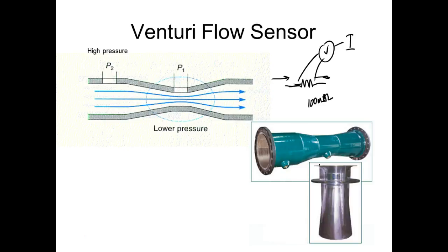Now your milliamp scale is probably going to have like a 100 ohm resistor in there, but you've got to remember that's milliamps, right? Even if 1 milliamp flows through a 100 ohm resistor, it's going to drop 100 millivolts, which is not going to be enough of a problem. And you can measure this. You can take your meter and put it on amps, and then put it across the 10 amp thing, and take another ohm meter and put it across there, and you can measure that resistance.